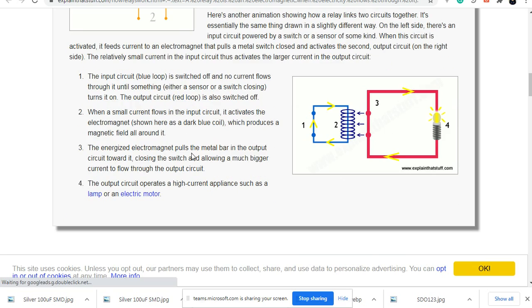Now there can be a device, similarly you can see over here what is happening. You can see a relay coil, and as soon as you turn on this switch, which can be a transistor switch, remember this is a transistor switch, you will have the device working over there. As soon as you have that energized coil, you can start any motor, any fan, or whatever. So from a DC circuit, you can control an AC circuit by using a relay.